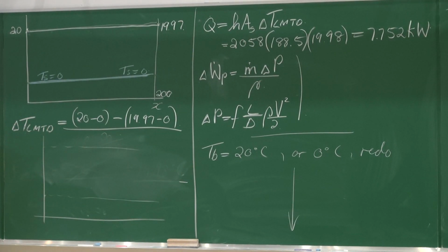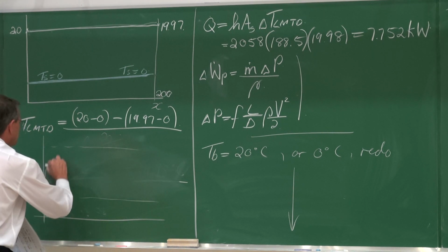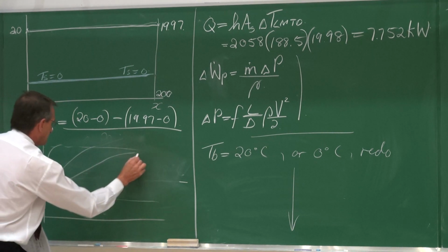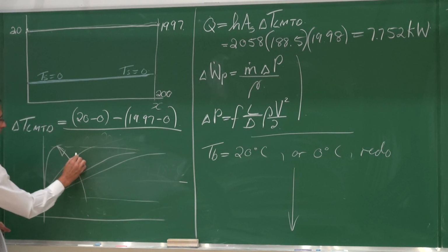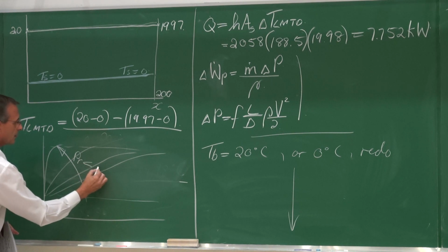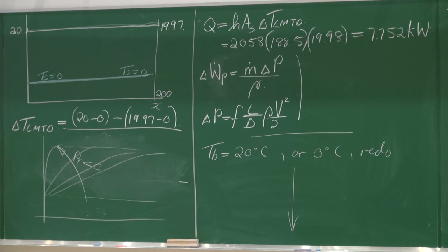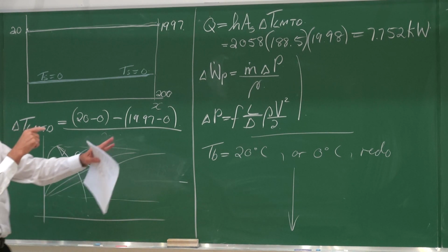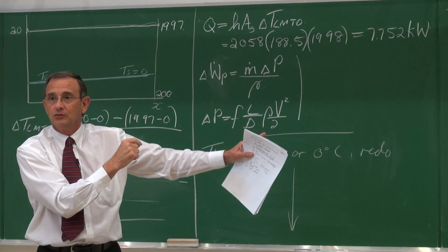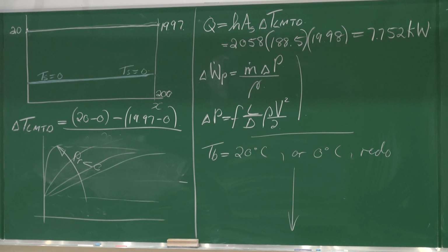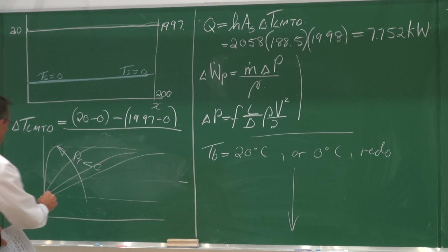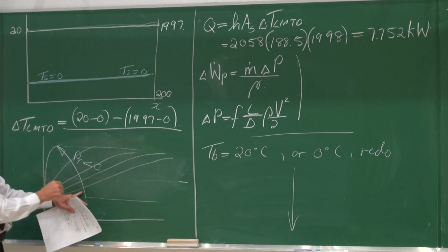The results showed typically something like that, and that happens if the Prandtl numbers become smaller. Do you remember? Heat diffuses very quickly. This example is a Prandtl number which is very large, so the heat diffuses very slowly. So we can expect rather something like that.